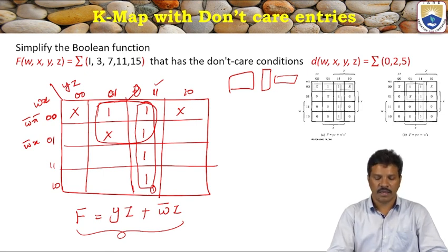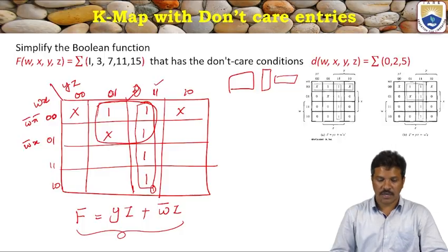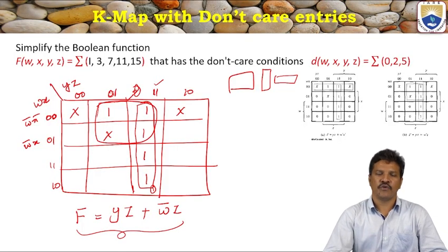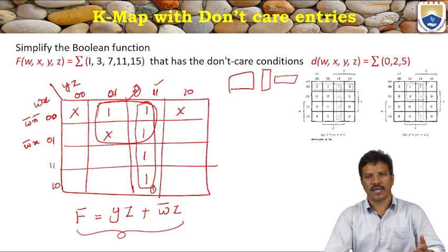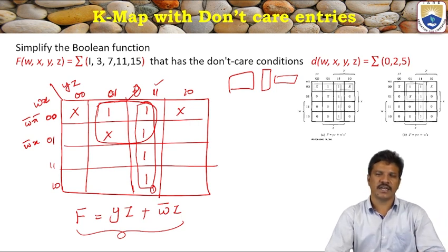This is the K-map with 4 variables, 5 variables, and even with the don't care. Even with 5 variables we can consider don't care. We can mark the don't care in the two 4 variable boxes and treat it as don't care along with the ones' adjacents. So this is all about don't care entries in the 4 variable and 5 variable K-map.